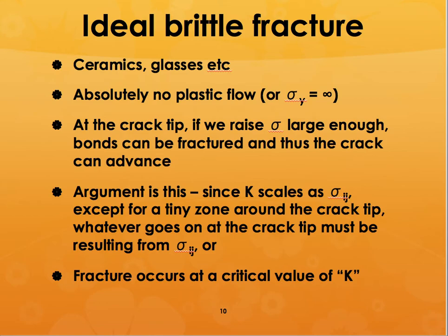So where is it more critical? It is more critical in the case of ceramics and glasses, which do not have any kind of plastic flow, or where sigma y is approximately equal to infinity. So at the crack tip, if you increase the stress large enough, then those bonds can be fractured and the cracks can just advance and progress further.